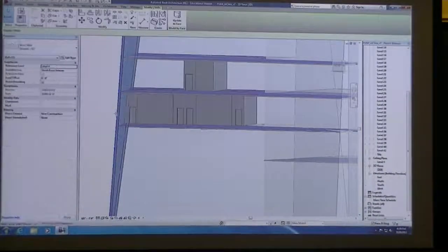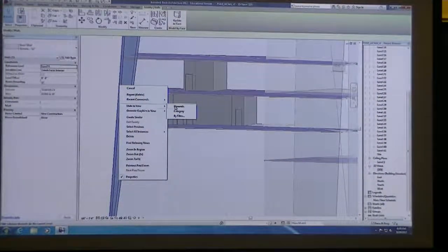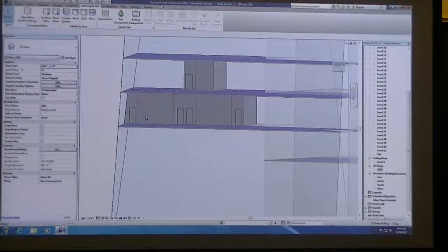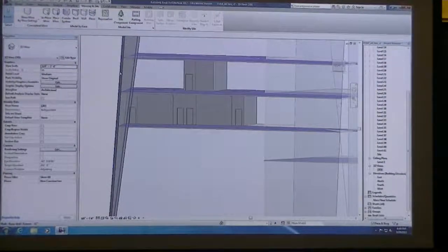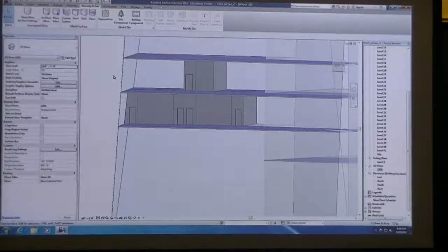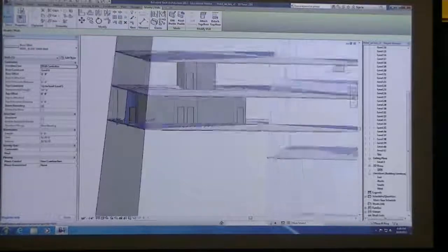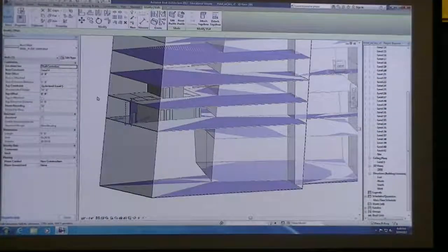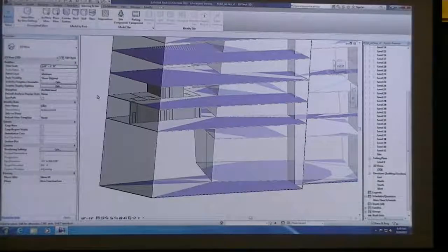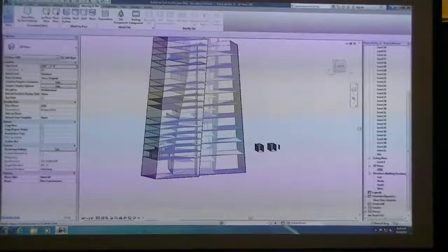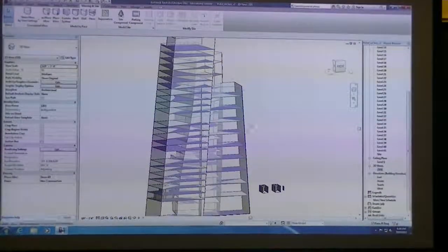And that will trim up that wall, and you can either keep this wall in place and hide it, so I could make a permanent hide. I could say hide in view elements just in case I ever need to bring it back. Or when you're done trimming all the walls along that whole exterior face, you could just click on that wall and delete it. And because you edited the profile, you're able to still keep that shape. So unfortunately, it's a little bit of extra work for trimming, but luckily you only have to do it on the exterior face and not all throughout.